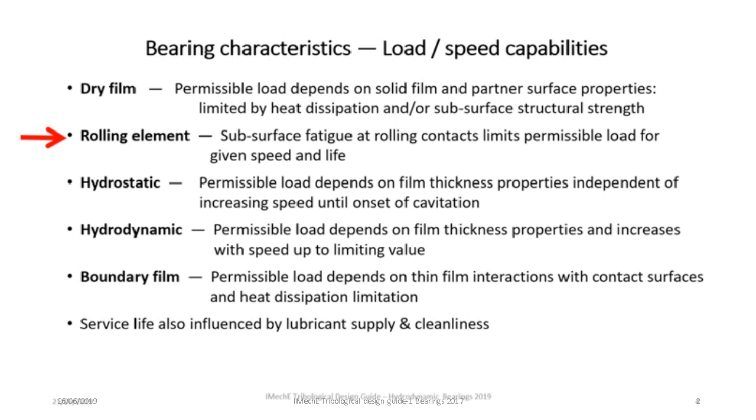The limiting loads and speeds of full film bearings can depend on the initiation of cavitation in the liquid film or on a reduction in the effective viscosity of the lubricant because of excessive temperatures. Of course, hard and abrasive foreign bodies in the lubricant, perhaps ingested from the external environment and not filtered out, can lead to much reduced bearing life through abrasion of the bearing surfaces.